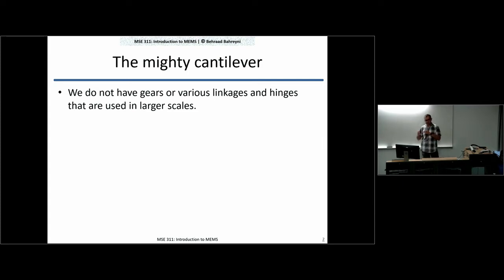The precision you have is much better than what you can get at microscales, where you have a device on the order of a few microns, and the gap between the structures is on the order of a few microns as well, right? So for example, if you make a gear set at microscales that can interlock and move, the space between the teeth of this gear has to be etched, so it cannot be below your lithography resolution, and you get that much backlash, okay? So in most situations we don't actually even have gears.